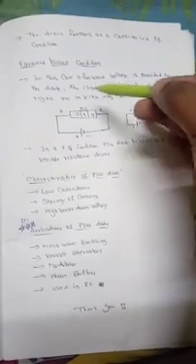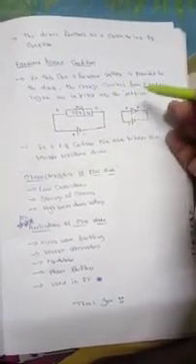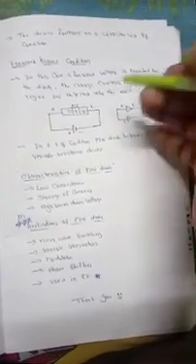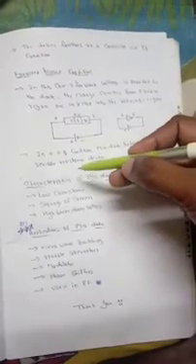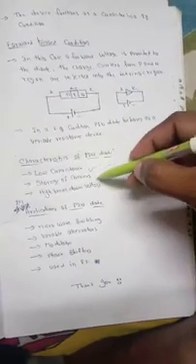In forward bias, the forward voltage provided to the diode causes charged carriers from the P and N regions to be injected into the intrinsic region, so the depletion region decreases. In forward bias, the PIN diode behaves as a variable resistance device. The characteristics of the PIN diode are low capacitance, stored carriers, high breakdown voltage, etc.